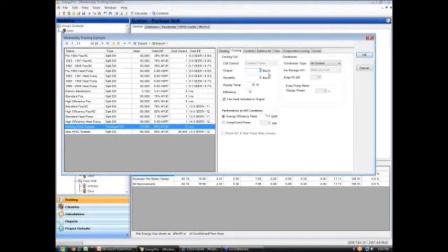So I don't remember what we had there, but my total output was, it's a 4-ton unit, 48,000 BTUs, 12,000 BTUs per ton. Most of this equipment has about a 75% capacity between output and sensible.